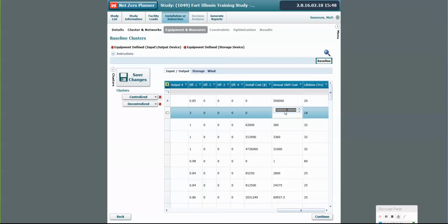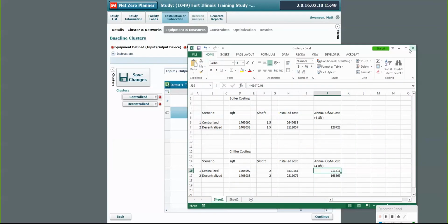Now, if you can collect records from the facility staff that are close by and they have good information on what the annual O&M costs are, then that's a perfectly valid way to go. That's usually pretty difficult to get a hold of. And we haven't been super successful trying to get a hold of that, at least at a planning level, to do it very quickly. So another way to go about this is to determine the approximate installation costs using RSMeans data, and then back out of that what the approximate O&M costs would be. And so I'm going to show a quick spreadsheet here.